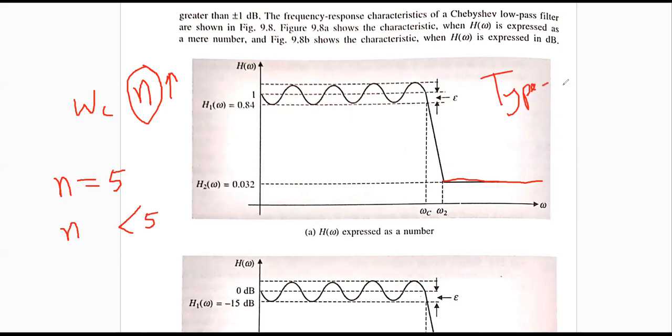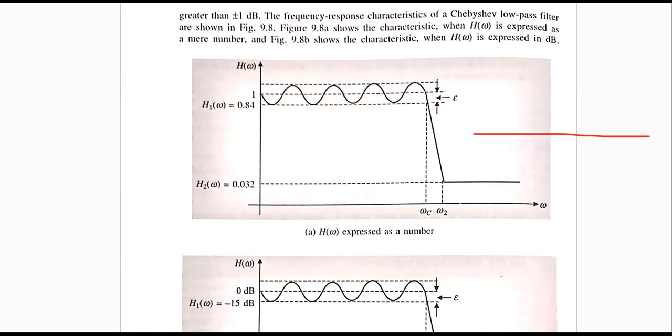And there is another Chebyshev filter called the inverse Chebyshev filter, or type 2, where the amplification gain looks like this. It will be monotonous, or a straight line, in the pass band, but there is some ripple in the stop band. So this is called the inverse Chebyshev filter. In an upcoming section, we'll talk about the inverse Chebyshev filter. Now we'll just talk about the Chebyshev filter.